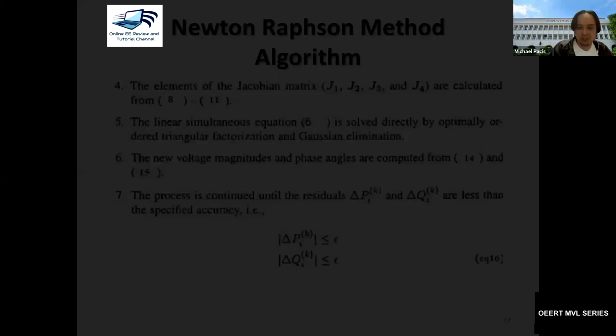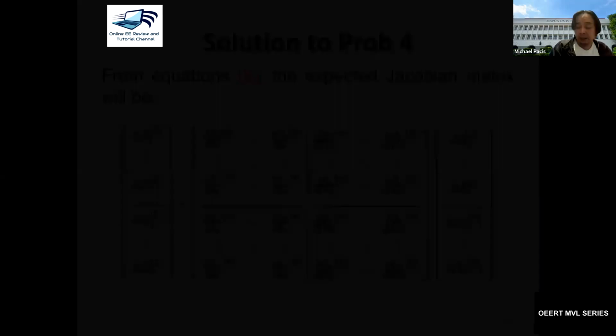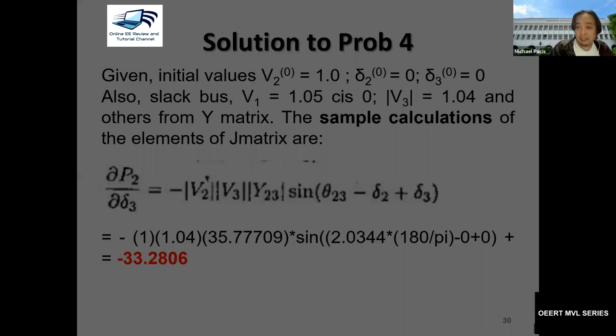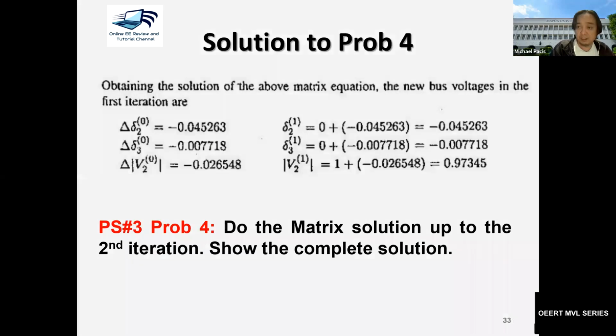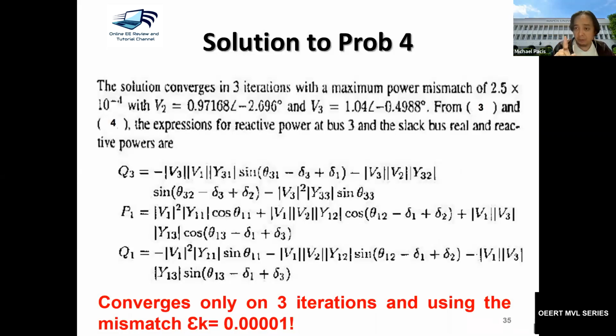Okay, now in this case, this is the solution in terms of the Newton-Raphson. It will yield with 3 iterations. And I solved it by using the computer, by using my algorithm in MATLAB. In Gauss-Seidel, it reaches at least 12 or 13 iterations. Imagine, 13 iterations before you get these answers here, which are eventually the same.